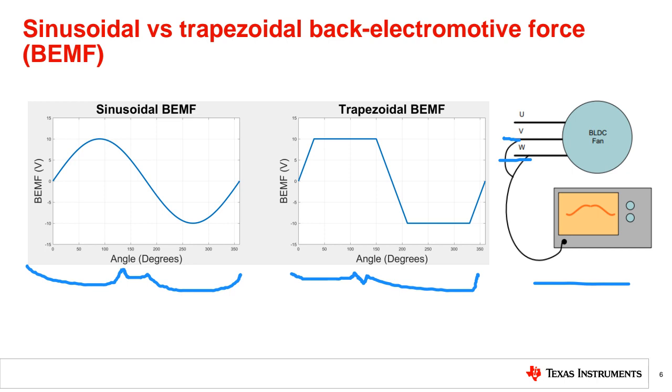This is an induction machine or permanent magnet synchronous machine. If you see trapezoidal back EMF here, like this one, this is called trapezoidal. This means that this is brushless DC. Every 6 steps we detect the commutation points using a Hall sensor. Okay.